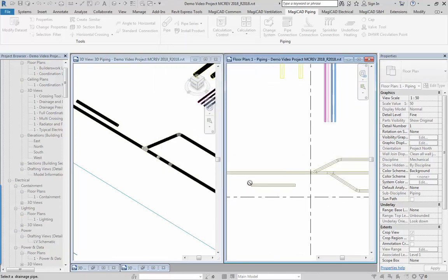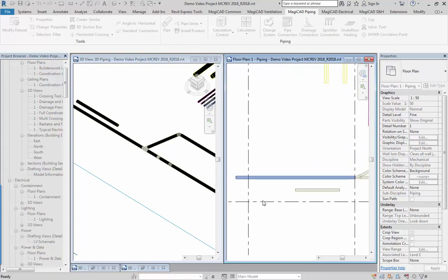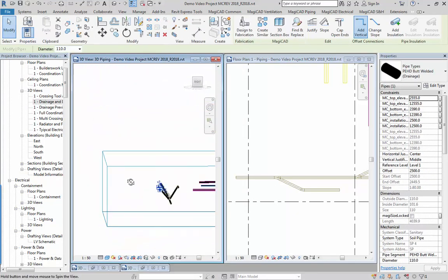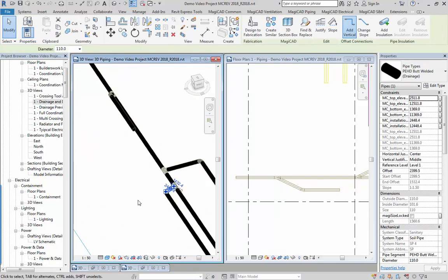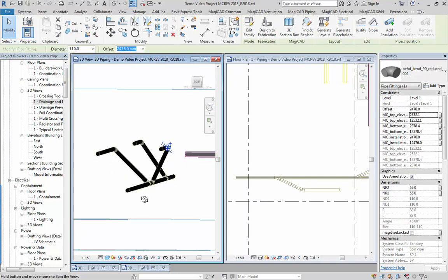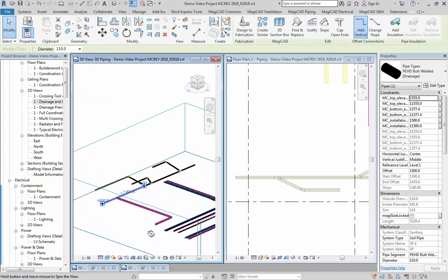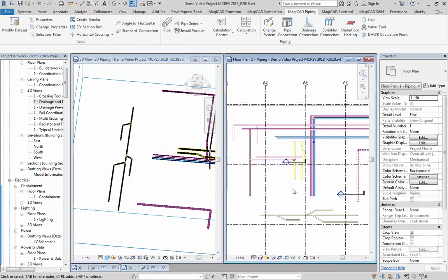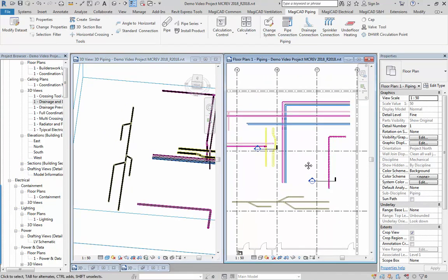So what I'm doing, I'm replicating how you would connect in a spine of drainage that drops from above to a certain level, and you can see in 3D how that looks. It puts the angles in there in accordance with that 45 degrees, and obviously rotates that fitting around to connect that up. So you can see it's all 1 in 80 drainage all the way through. So that's another decent pipe connection tool that we can use to create these sort of awkward connections now and again. Okay, so also what I want to look at is the pipe modeling tool.